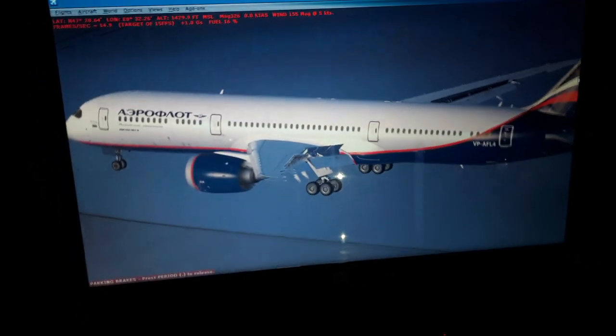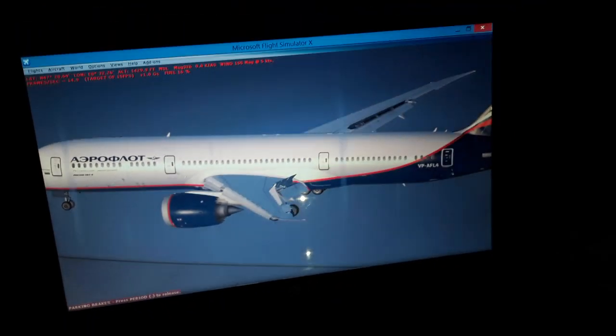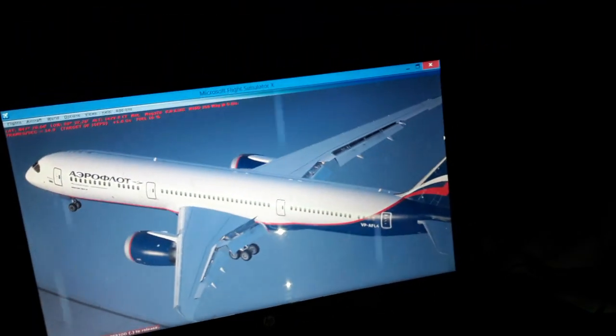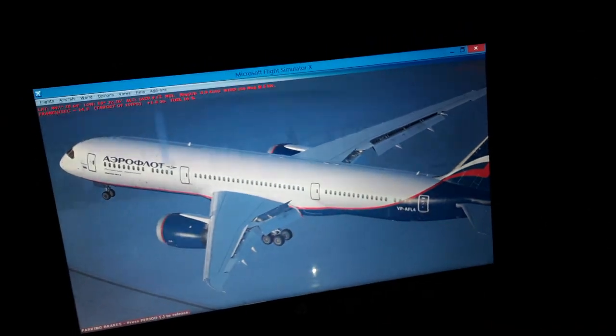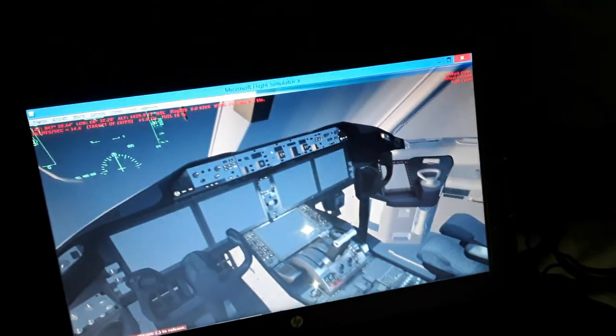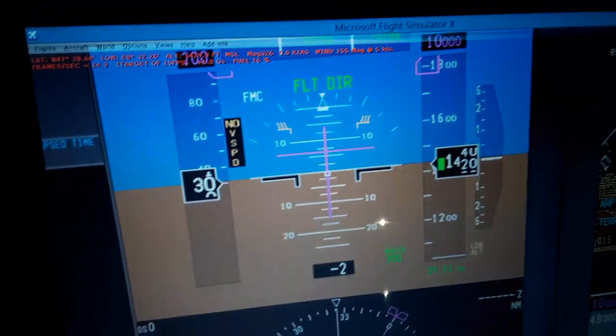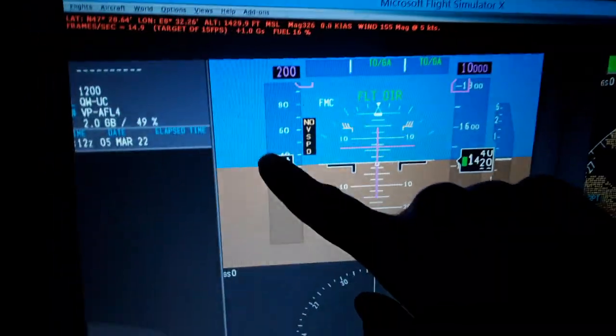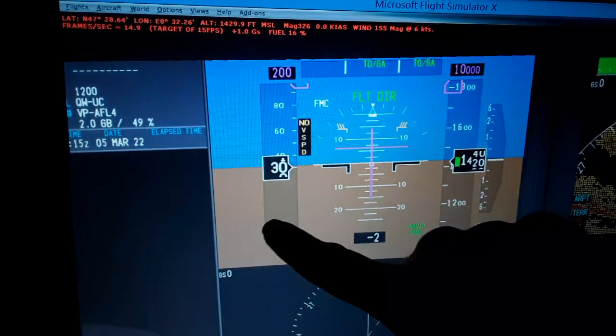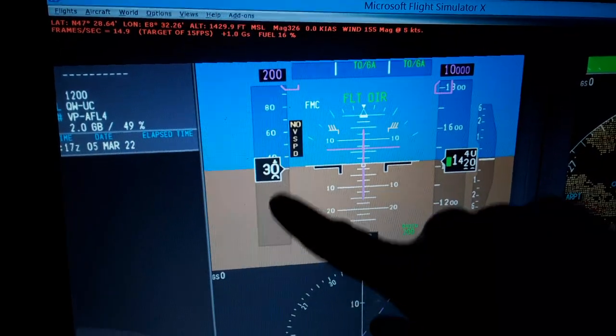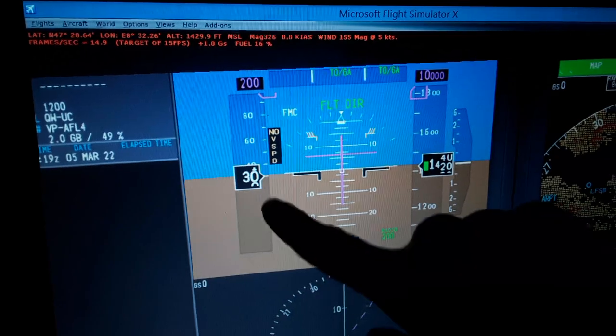And also altitude of flight and other factors. So you can see also we need to avoid the stall as we fly, because it's going to make the aircraft fall. It is one of the main reasons. So you can see here we have the airspeed tape, very important. In the primary flight display, as I told you, you need to have the indicated airspeed always above the yellow and the red indication here that shows you the stall speed.